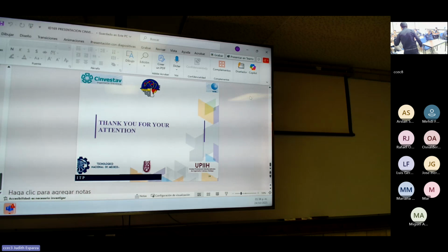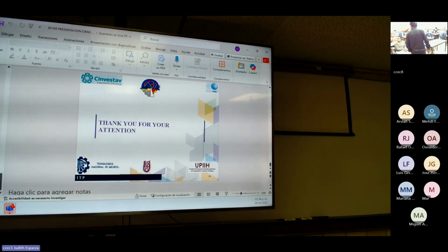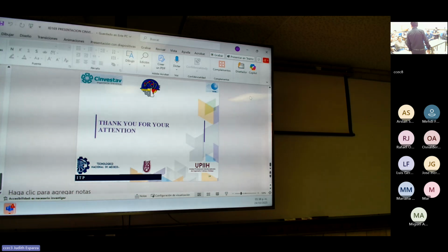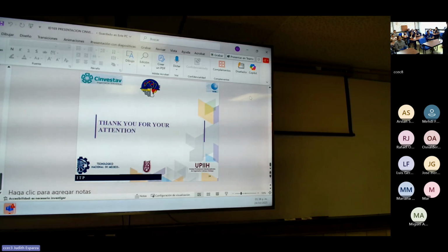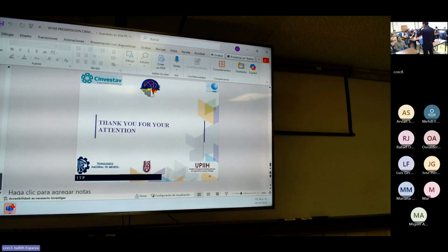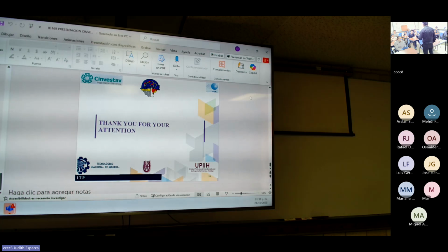I mean, your model is only a single degree of freedom. However, the boundary conditions, because looking at your boundary conditions, your connection to the ground is not symmetric. So you have a square with some screws. You have non-symmetric performance, and on the top you have the wind turbine, and that wind turbine can rotate. So in different directions, you will have different components, different values for the first mode shape.